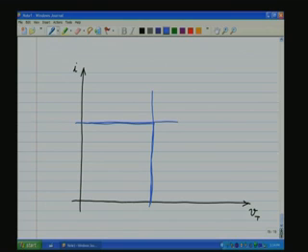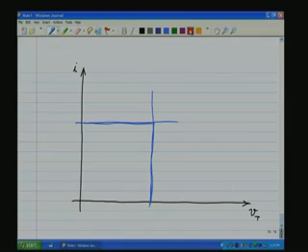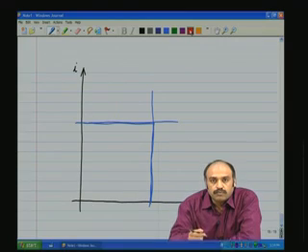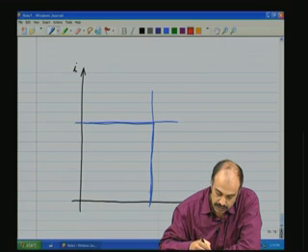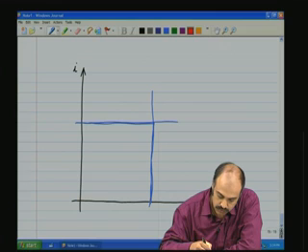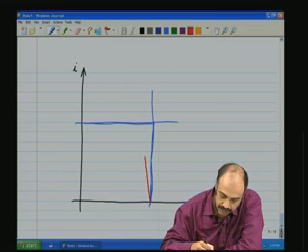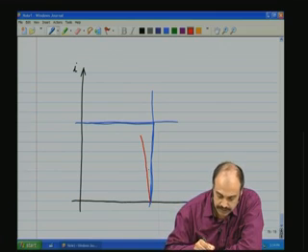But there are some non-idealities in the solar cell, that is, it also has shunt resistance which is finite, it has a series resistance which is also finite, non-zero. The series resistance we know affects the voltage source parameter. So, instead of being vertical like that, the voltage source is going to deviate from the vertical because of the series resistance, or should I say the I R_S drop.